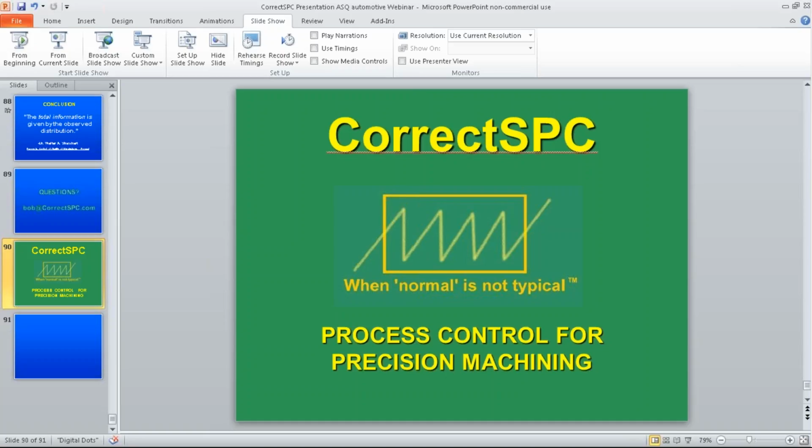But what's important to understand about this is that you've probably been beat up before by people saying, well, your process needs to be centered, and of course it can't be, because you have to start with it either small or large, depending on whether you're doing an ID or OD, to allow the tool to wear. So you still have a tool wear issue. You may have a little more variation based on material that participates, and sometimes that can mask what's going on, especially because your tool wear now isn't over an adjustable period of a week or a day or an hour, but months. But in the long run, you do have the same type of thing, where if you were to track your dimensions, and you'd have to track the exact same locations.